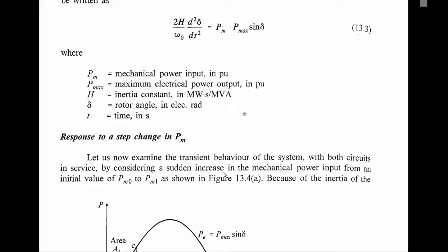There are three situations. To model that, we need to know about the swing equation, which we will solve to find how our rotor angle changes for various clearing times.